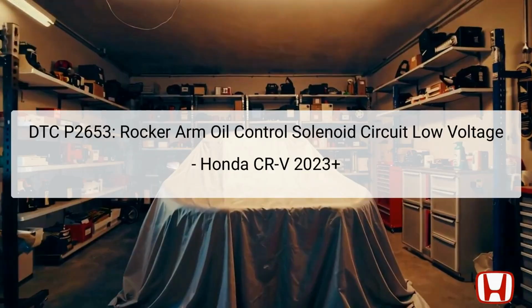The Diagnostic Trouble Code, DTC P2653, indicates an issue with the rocker arm oil control solenoid circuit, which is fundamental for regulating oil flow to the rocker arms. In a Honda CR-V 2023 and newer models, the rocker arm oil control solenoid is integrated with the rocker arm oil control valve. Its primary function is to manage the oil pressure within the engine to optimize performance and fuel